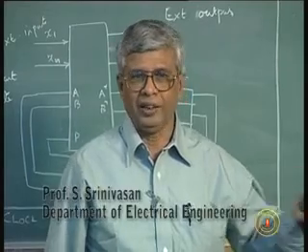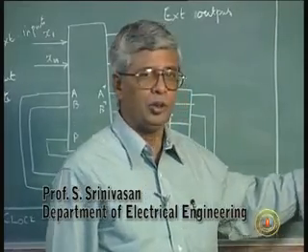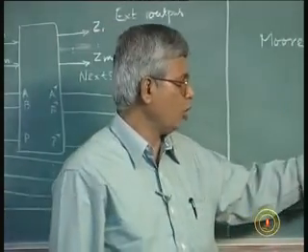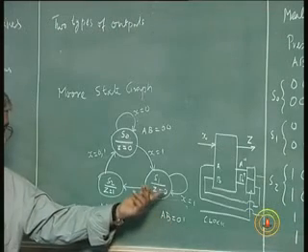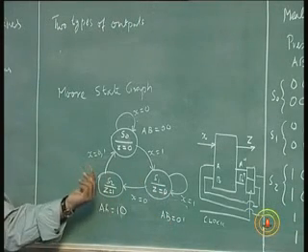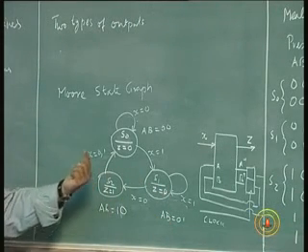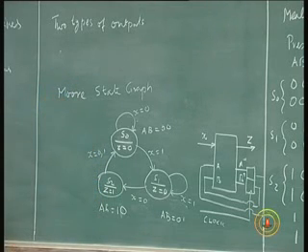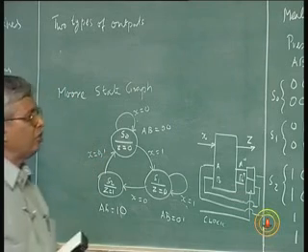That should be reflected. So you can't say it's a state variable. Whatever the state variable is, for example in this case, state variable 0,0 gives an output of 0, 0,1 gives an output of 0, and 1,0 should give an output of 1. I should indicate that condition in the state graph, and also design for it in the output. So now the Mealy state graph has been modified into a Moore state graph, which is very easy.